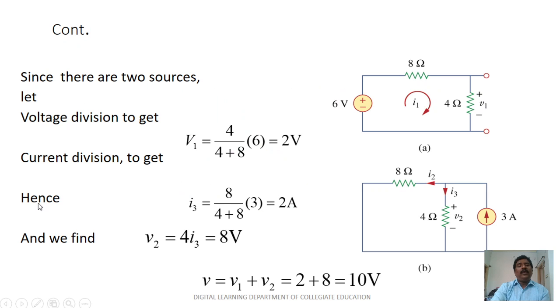So looking back to the previous sums, when I want to use any method, if you have any voltage sources, you short that, and current sources open. Those steps you can follow here. So first I want to keep the 6 volts supply as it is, and remove the current source. This is the current source, so I can open the current source, so I can calculate the current or voltage.